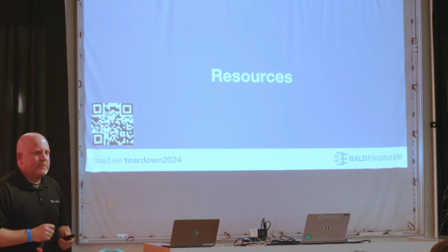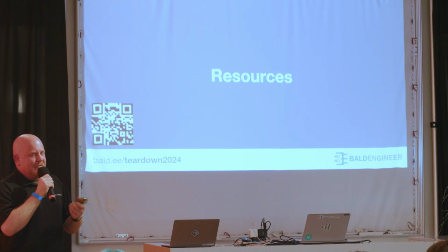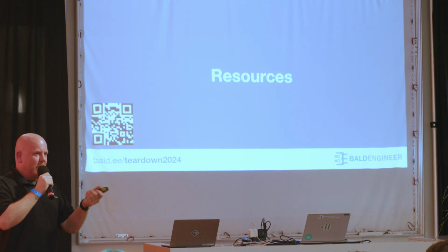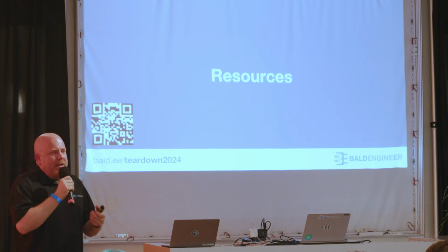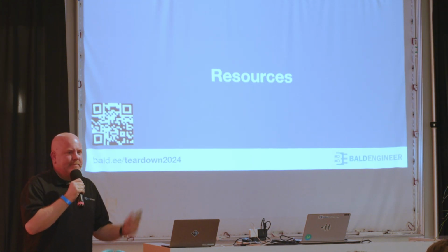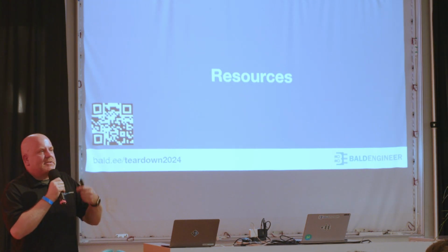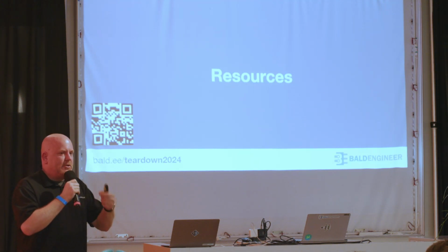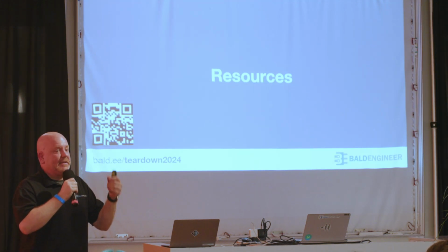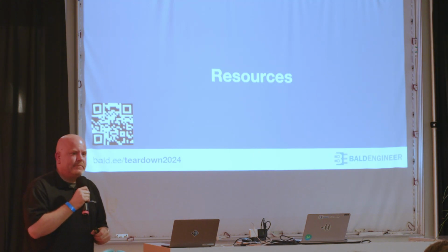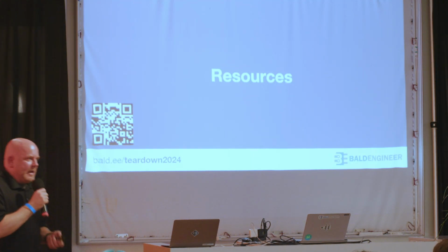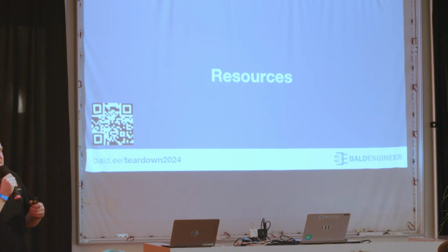The question is, the reason they don't care that it works after 10 years is because they don't care. I'm being a little bit facetious, but the reality is the caps are actually still doing what they were supposed to do. They're supposed to wear themselves out because, in theory, it got hit with a bunch of transients and it wore out, and that's okay. But I've never heard of a product losing its FCC cert 10 years later because its EMI filter wore out.